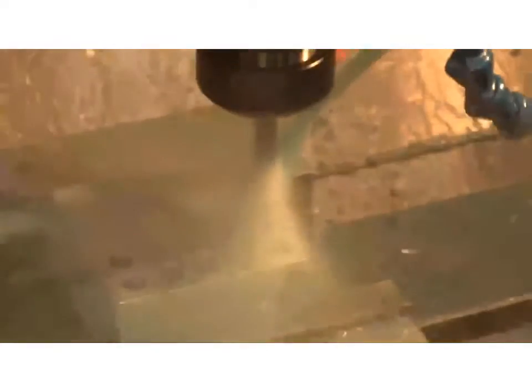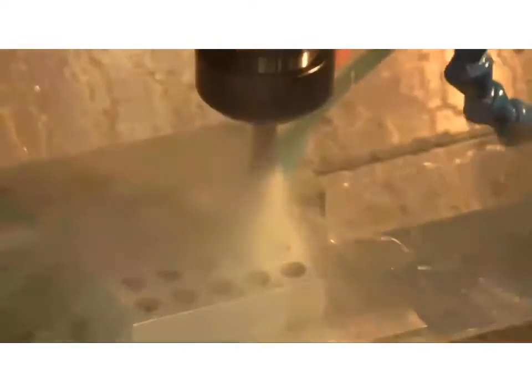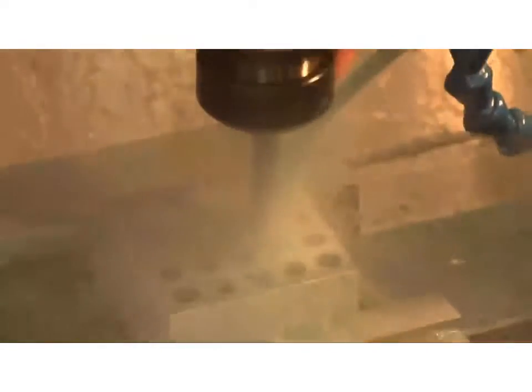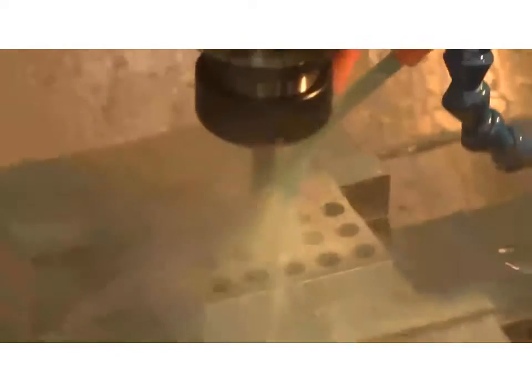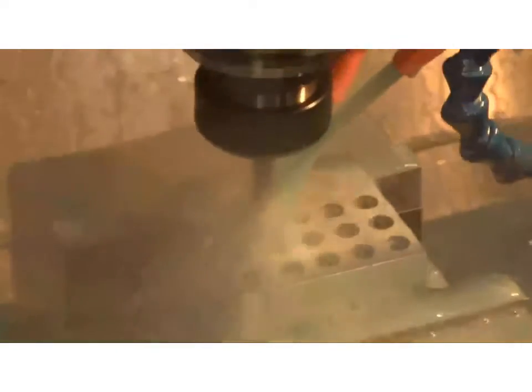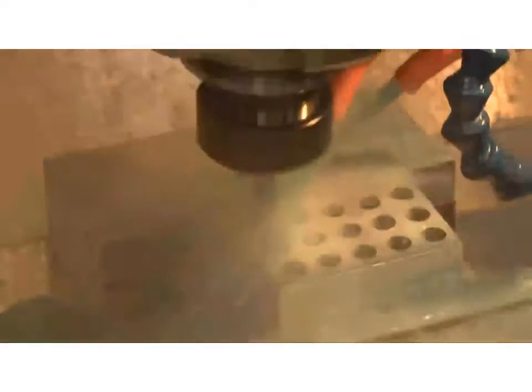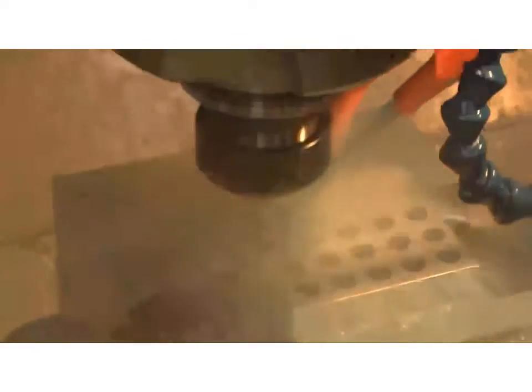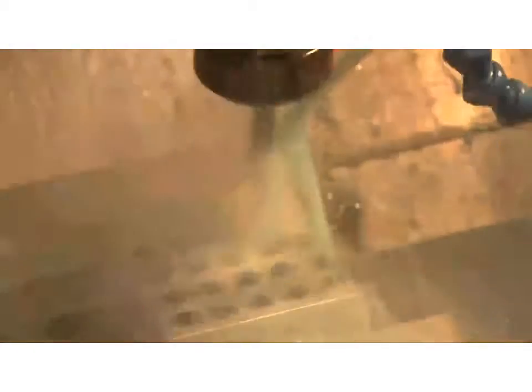The 3-tooth drill, like I said, is a really nice drill for staying on location, staying on size, and processing quickly. So even if you don't have the latest machining centers with through spindle coolant, it doesn't mean you can't take advantage of some of this technology.